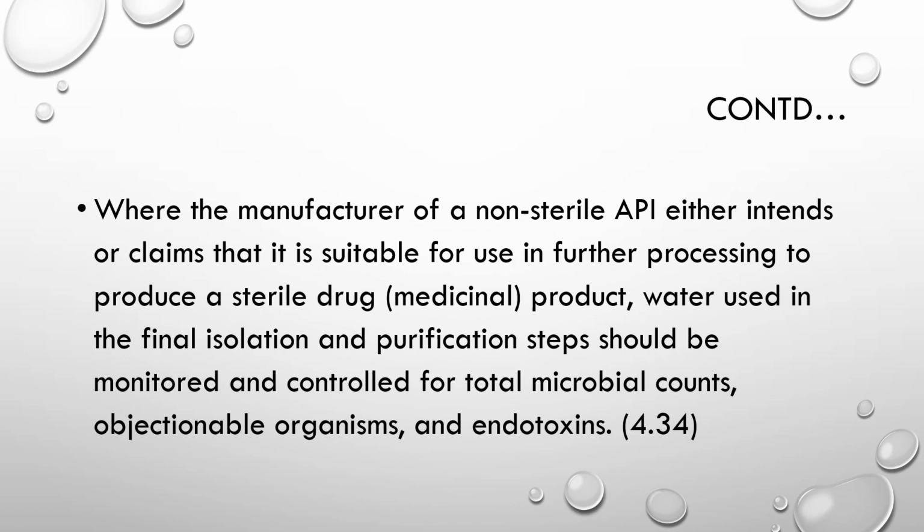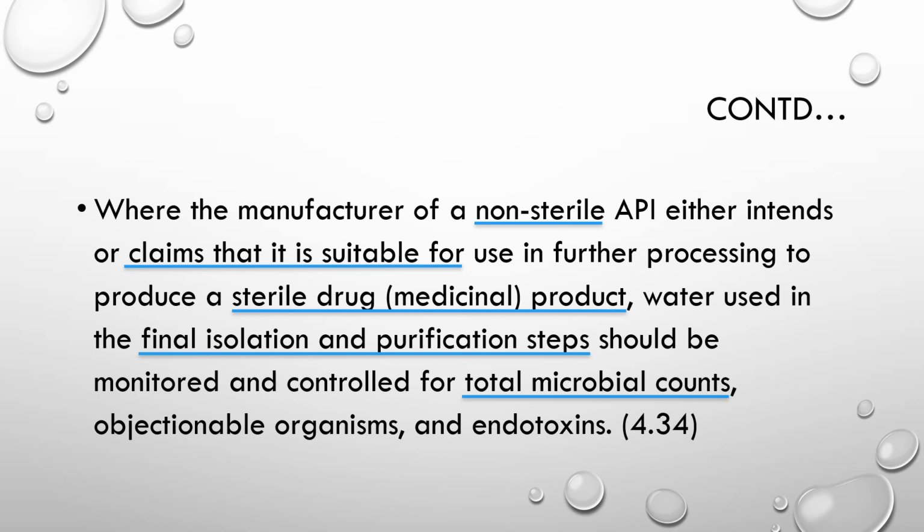Let us see what section 4.34 prescribes. Where the manufacturer of a non-sterile API either intends or claims that it is suitable for use in further processing to produce a sterile drug or medicinal product, water used in the final isolation and purification steps should be monitored and controlled for total microbial counts, objectionable organisms, and endotoxins.